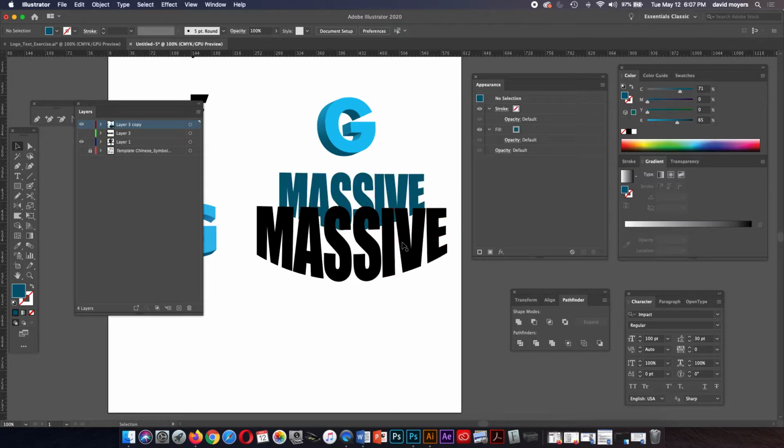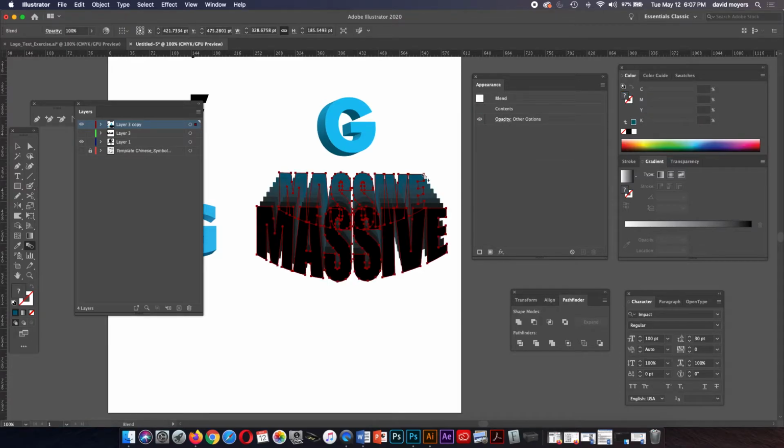Okay. Now what we're going to do is a blend. Mind you, I made a copy of this text here, and we're going to paste it again, so you don't want to copy anything else once you've done all this. So we're going to get our blend tool, and we're going to click on the end of this E. Okay. And then I'm going to go back, and you should get a plus sign, hopefully. If not, then you should click and then come back up here and get a plus sign. But you want to click on the same exact points. And what this will do is create a blend. Now, right now, it's a choppy blend.